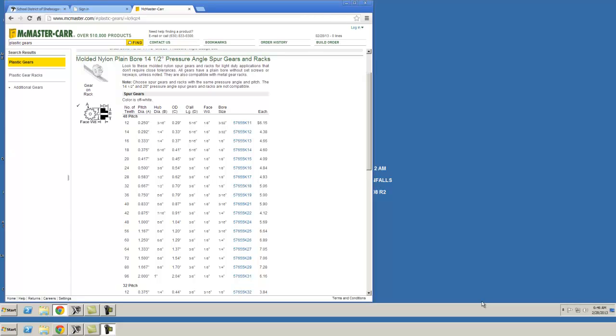Okay, again, we'll go back, we'll sketch. If you don't know the decimal, again, remember you can put the fraction in. Now I'm going to extrude that. Extrude that up 0.25. Accept that.